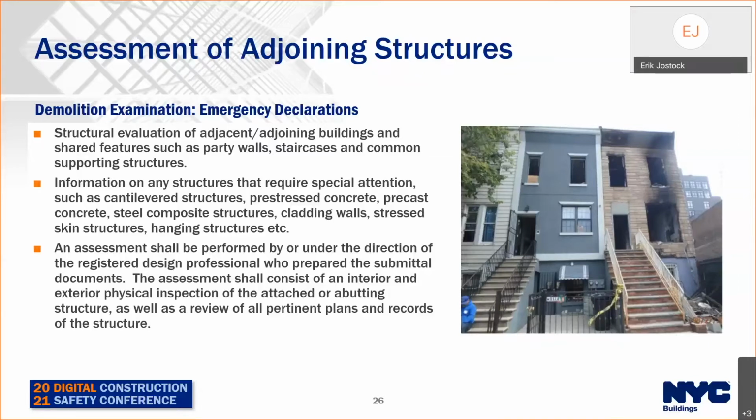An assessment shall be performed by or under the direction of the registered design professional who prepared the submittal documents. The assessment shall consist of an interior and exterior physical inspection of the attached or abutting structure, as well as a review of all pertinent plans and records.